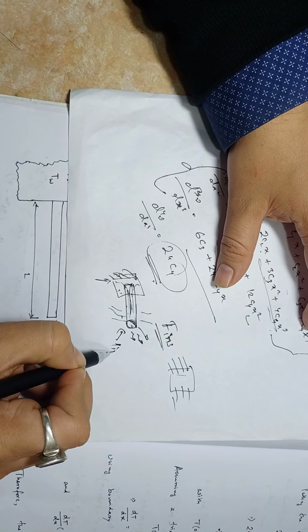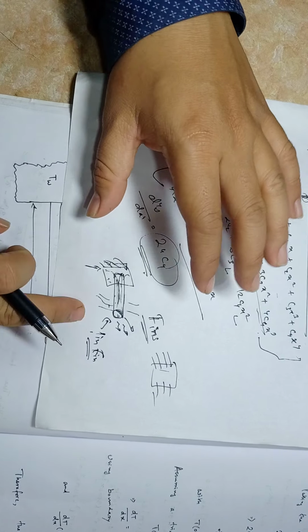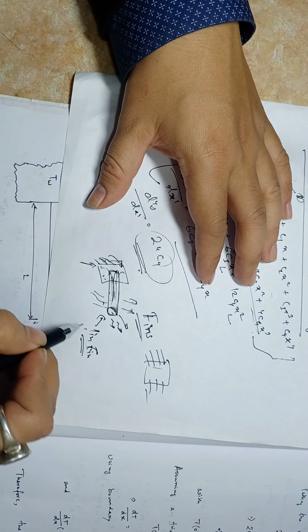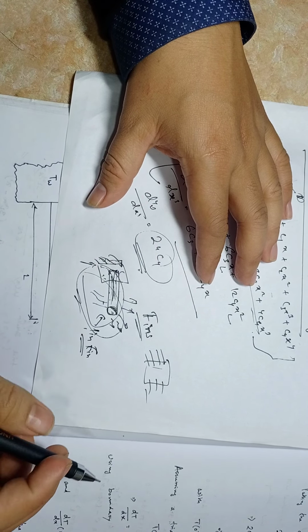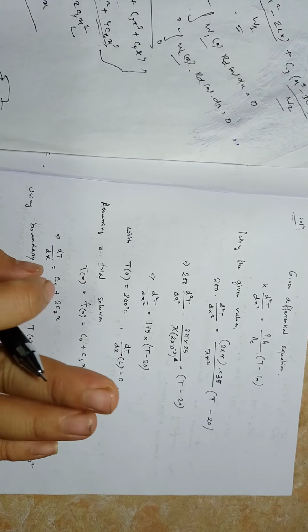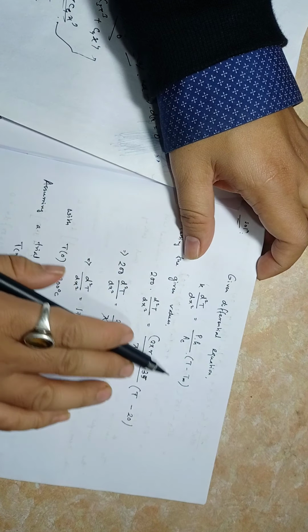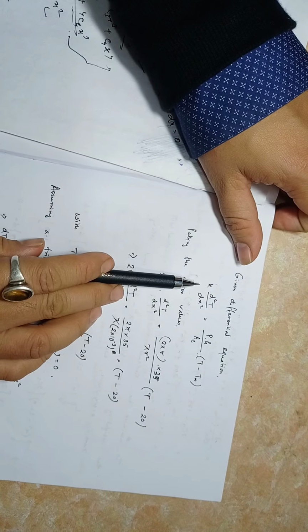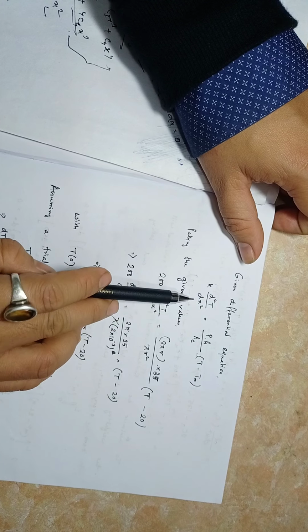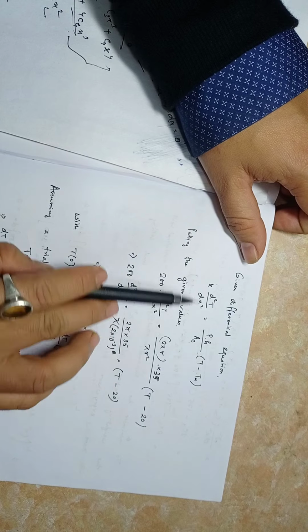So this is called a pin fin. This is a kind of pin. From the pin fin, heat is being radiated. This is an ordinary differential equation. The differential equation for the heat transfer is k d²T/dx² equal to (P h / A_c) into (T minus T infinity).